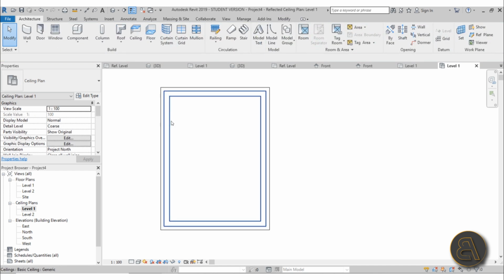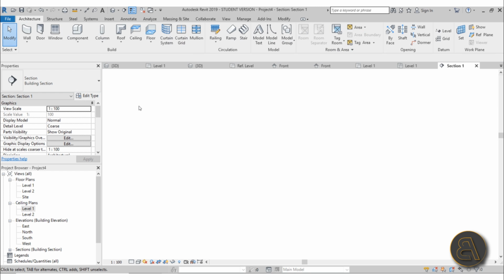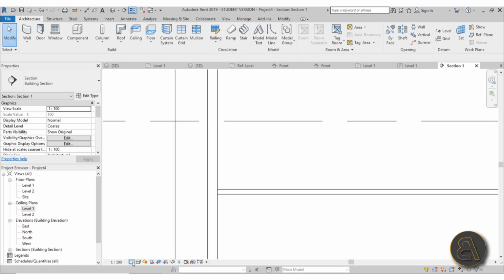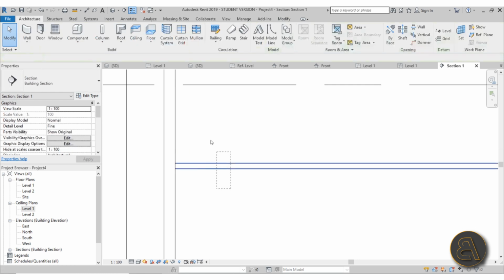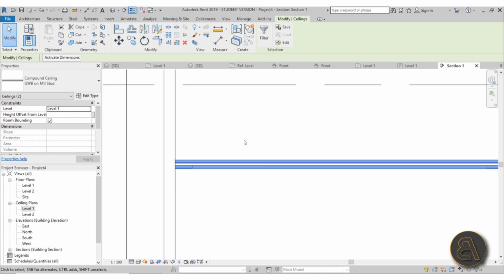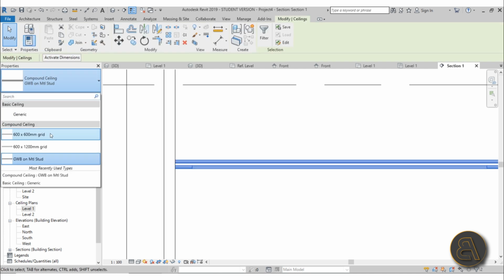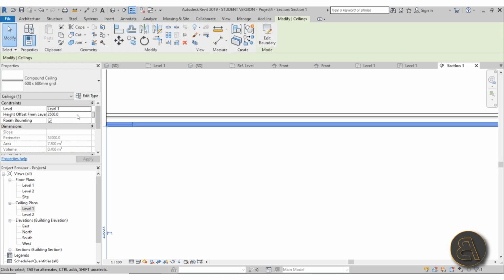Now the thing is with these ceilings, if I go here with a section and cut a section through it and open it up, yeah, if we go here to find, these default ceilings are usually really thin. So I'm just going to select both of them and maybe go with this metal stud ceiling. Yeah, that might be too thick. So let's try this one. It's a bit thinner. And yeah, let's bring this one a bit lower still. So maybe 45. So 245.